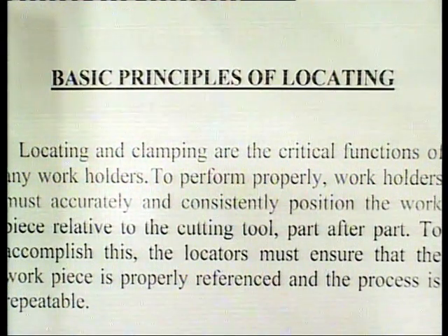So, basic principles of locating. Locating and clamping are the critical functions of any work holder. To perform properly, work holders must accurately and consistently position the workpiece relative to the cutting tool, part after part. To accomplish this, the locators must ensure that the workpiece is properly referenced and the process is repeatable.